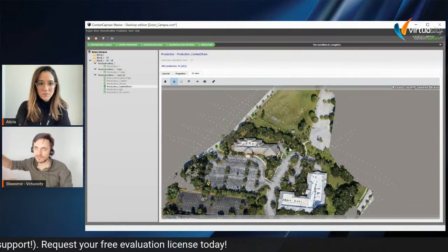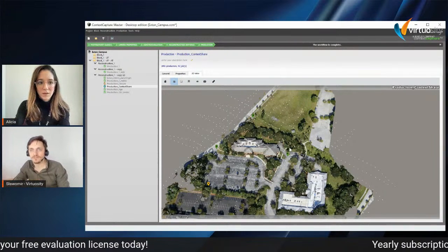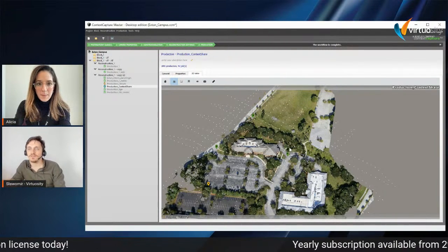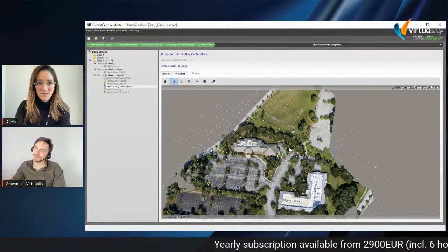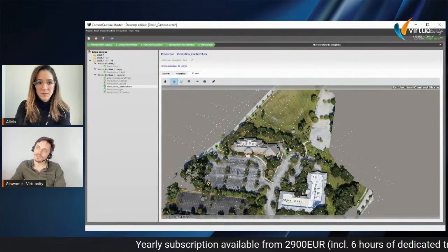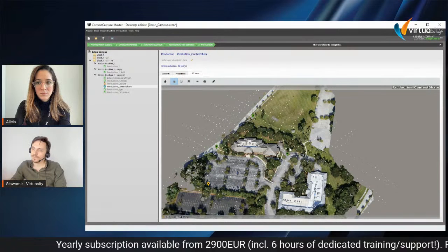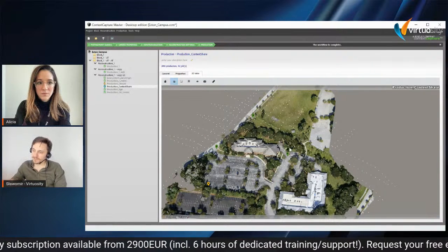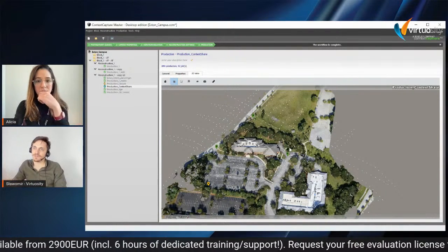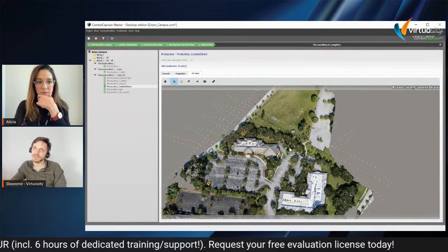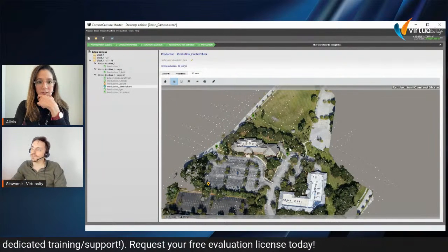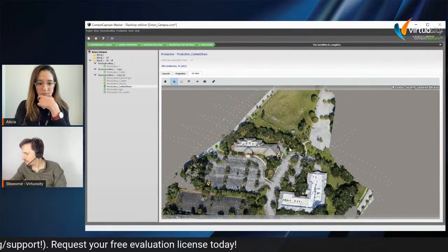You will just get a ground level, ground terrain model, and it will be much more simplified. Then you can create, for example, a contour map out of that, just automatically creating contours with, let's say, an interval of the major contours, with automatic labeling, also with a smoothing factor.